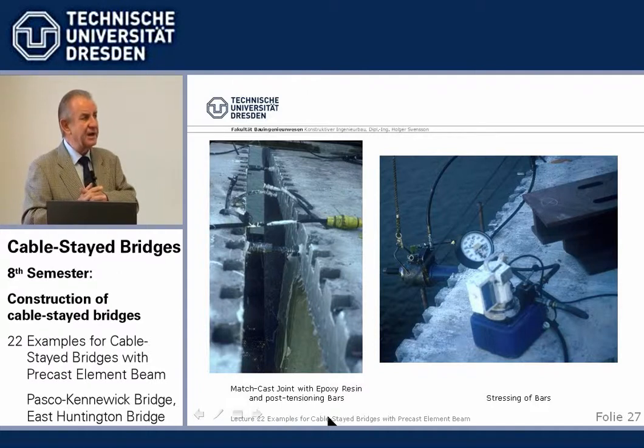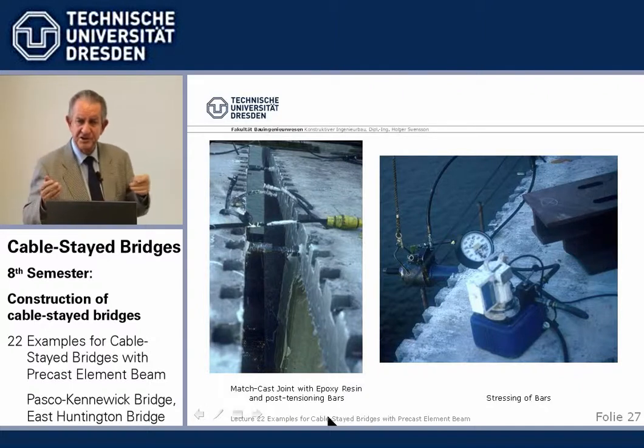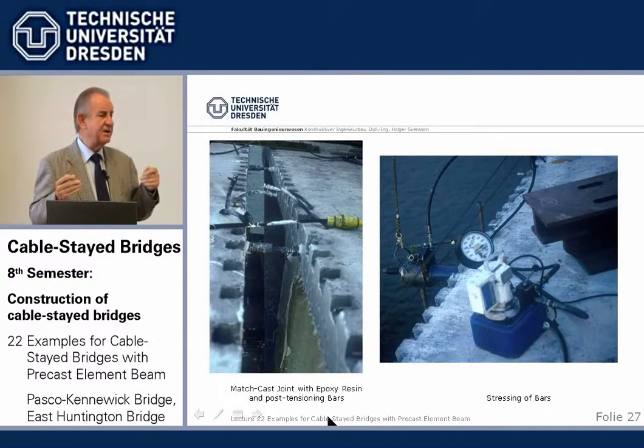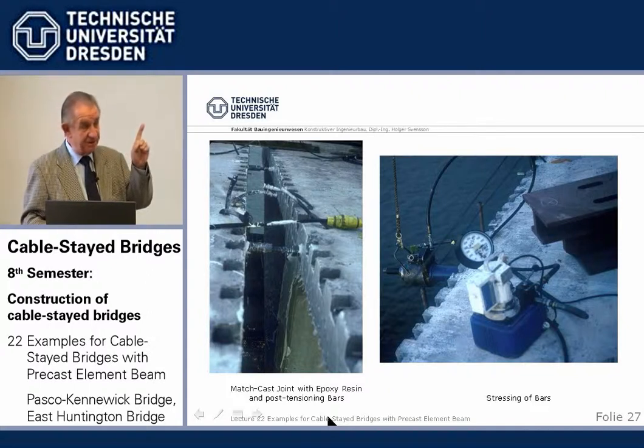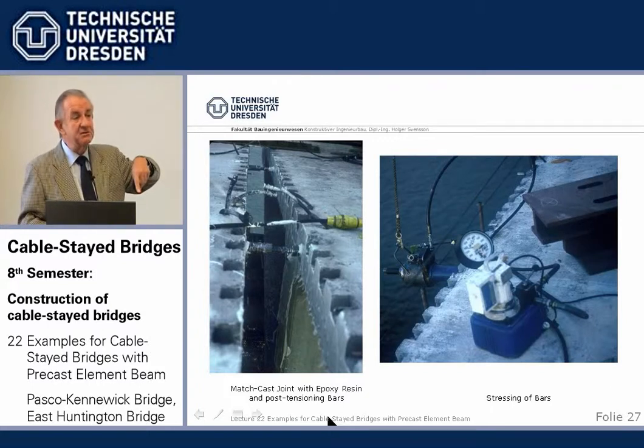Later on, people said, well, this epoxy and all that, that's expensive, especially the French. Jean Muller, for example, my friend, built the Key bridges in precast elements, match cast, without epoxy. Said, what? Epoxy, we don't need it. Theoretically, yes. But I've been in Key bridges and others, and sometimes you can see the sun look through the joints where they do not fit as tightly, which means the water's running through. And so I still insist, use the epoxy.